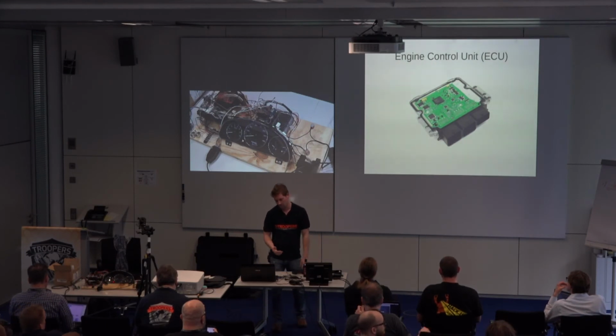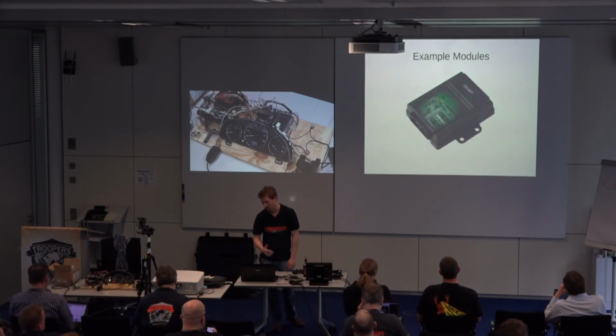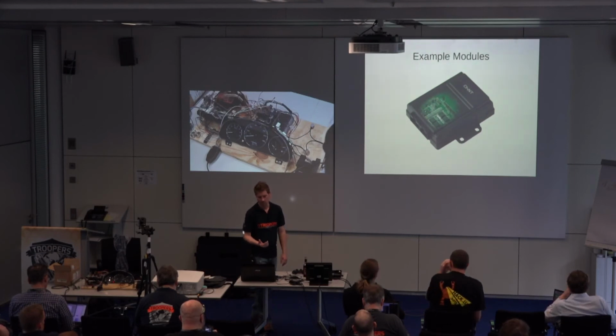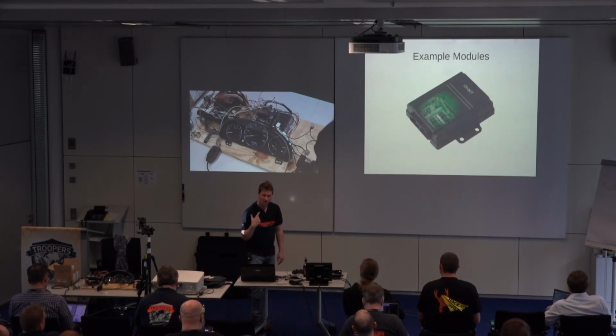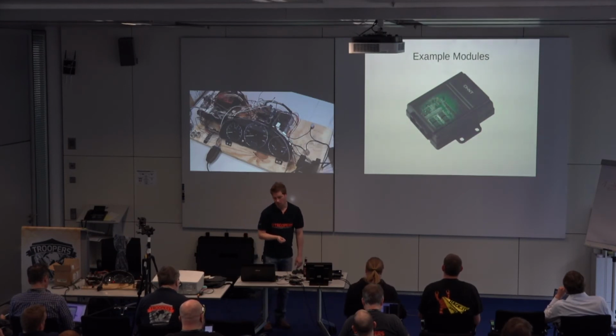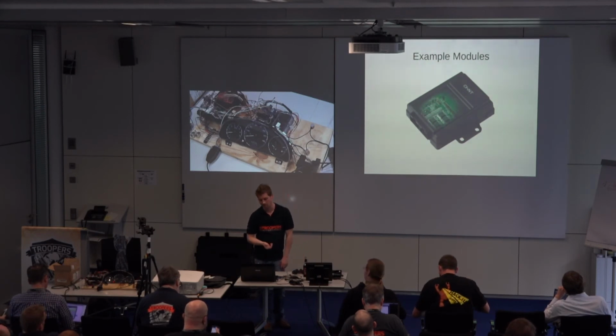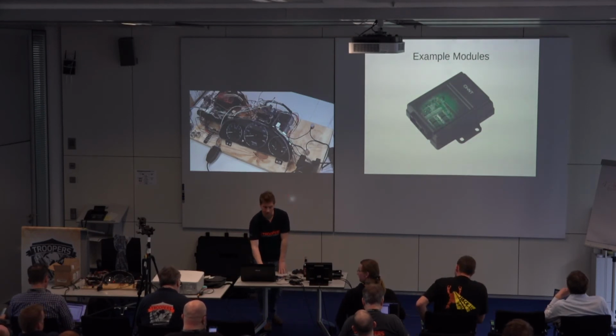Other ECUs are typically in module type stuff, like that's a body control module. There's a bunch of different modules, there's a bunch of different sensors. Again, getting anywhere on the wires will get you actually access to stuff. An interesting one is oftentimes going between your body control and your ECU, there's bus lines that will connect those two that are not exposed to the OBD. If you see a line that's not exposed, those are great ones to sniff on. That's typically where the key negotiations happen, that kind of stuff.